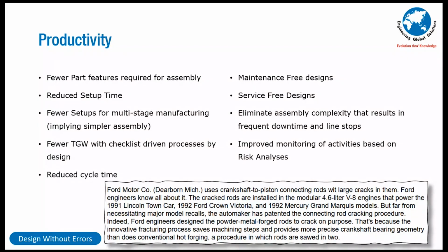The moment you break it, it will split into two pieces arbitrarily. Then when you put it together, they will fit as if there is no parting line. So the methodology to break it, they patented it. Till today, it is in use. Honda and other people have adopted it by paying royalty to Ford for that technology.